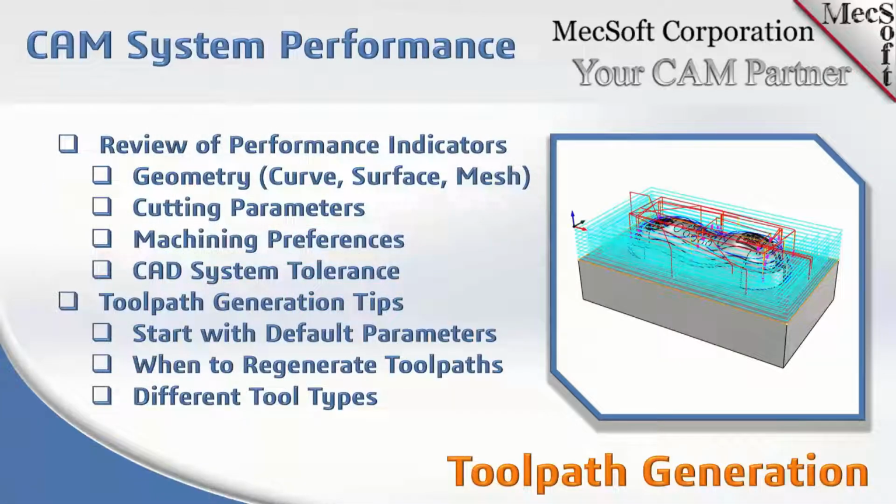Now we're going to look at the generation, toolpath generation. So what are the indicators for the length of time it takes to generate? Obviously, we talked about geometry, curves, surfaces, and mesh. That's going to affect your regenerating times. Your cutting parameters are obviously going to affect that, and there's a few parameters we're going to look at in just a second, which are major contributions to the time it takes to generate a toolpath, as well as the machining preferences, and obviously your CAD system tolerance.